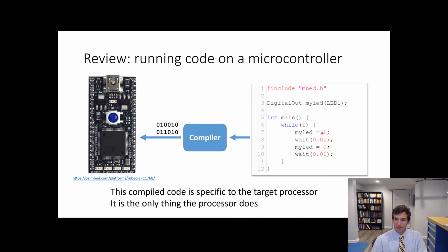And so we're going to set the LED on. We're going to wait a bit, turn it off, wait a bit, and turn it back on. Okay, and so this simple little program here is never going to stop. And I never wanted to stop, right? The intention of purpose-built hardware like this is to do a job, do it well, and do it forever. So once I'm happy with this code, I'm going to run it through a tool called a compiler, which is going to take this text and based on the rules of the C programming language and a knowledge of the piece of hardware that I want to run it on, it's going to literally turn this thing into a series of ones and zeros.